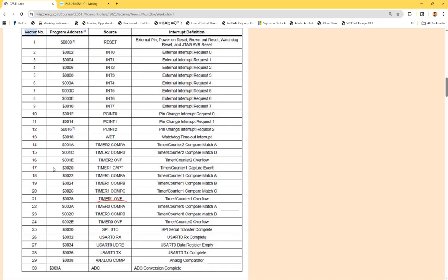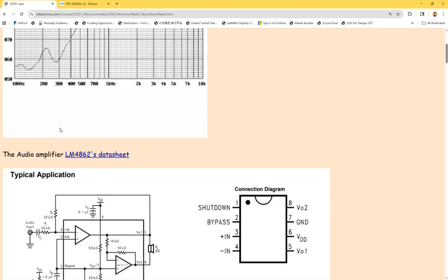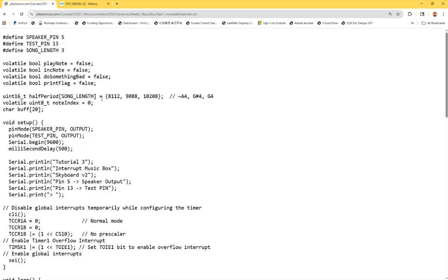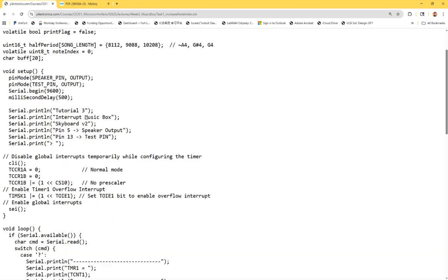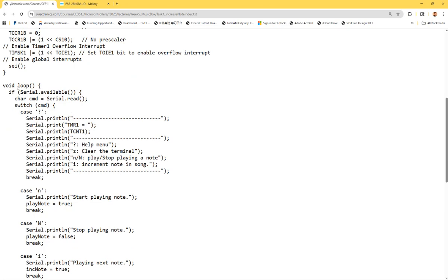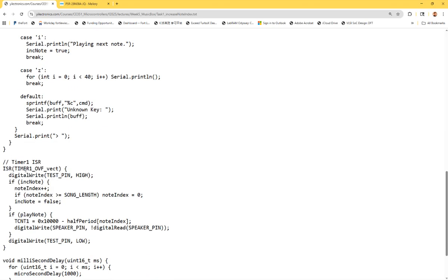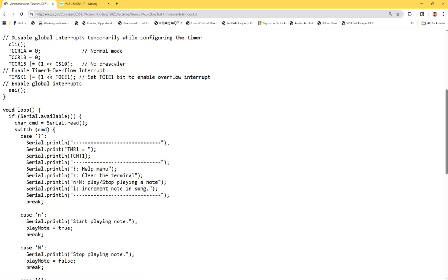Interrupt is a new concept. So whenever you are running the code, if you look at the code, it has a permanent loop, right? Including this Arduino microcontroller, but also other ones as well. In other microcontrollers, it's called main. It's a main function. But this one uses a loop function instead. Okay? So the loop function, if you don't have any interrupts to interrupt it, whenever it finishes the setup function, it's going to get into the loop function and keep cycling back and forth inside. It's a permanent loop.